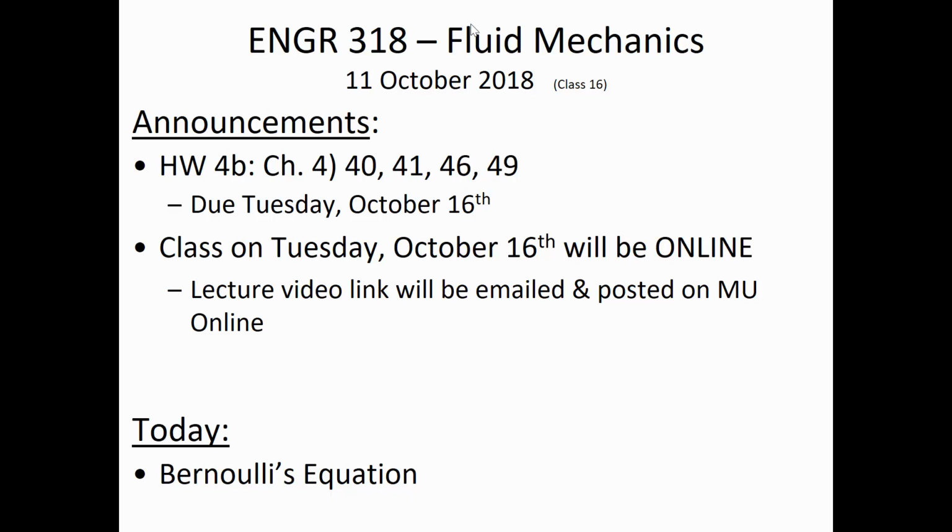All right. So Bernoulli's equation is going to be a new way for us to look at how pressure changes when water is moving. Remember, the hydrostatic equation told us pressure changes just simply as a function of depth. And Euler's equation told us what happens to pressure when there's local acceleration, meaning that the velocity is changing with respect to time. Bernoulli's equation we're going to use when there is convective acceleration, and it'll tell us what kind of pressure changes we can expect to see in cases of non-uniform flow.